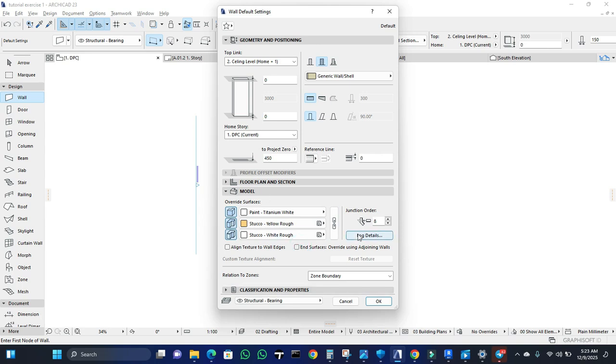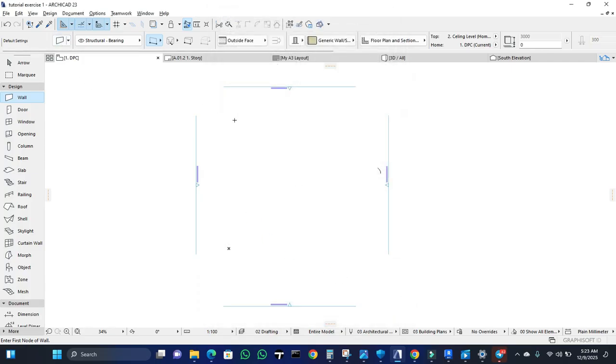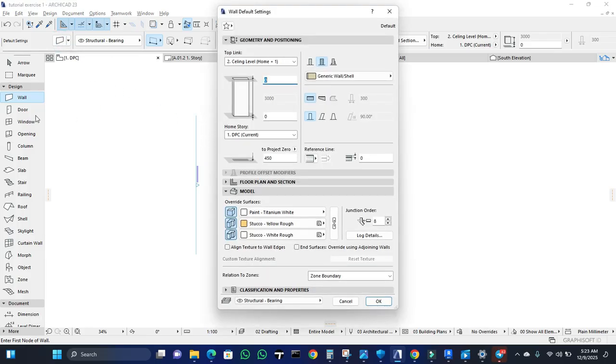So that's the default. This is how it is on default. But then when you come to your ArchiCAD, when you click on the walls, you click on that settings. Make sure that you set your wall to structure basic composite structure. Then there are different types of walls here. So this is the type of wall we are going to be using, the first one here.